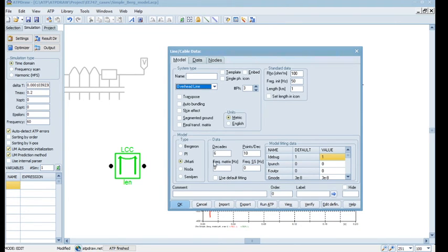So here, like JMRT, what is the order, how to put it? In a way it has a subroutine which calculates order automatically, but you need to specify till what range you want to model this. So you say, okay, I want 6 decades, means 6 tenths of frequencies, and how many points you want to fit, at what frequencies, and so on. And what is the starting frequency, and what is the steady state frequency you'll eventually end at, and so on and so forth.